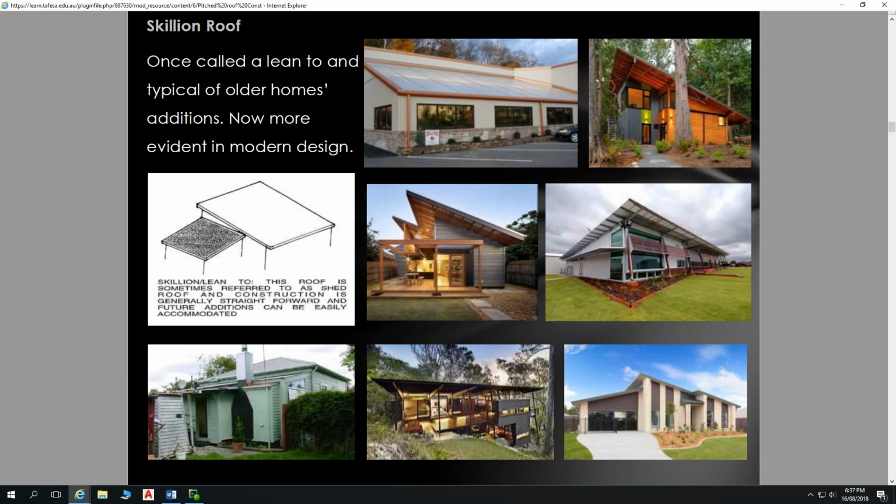So timbers that are durable, because they're still exposed to a lot of weather, and typically our engineered timber, all of our glulam beams and LVLs, don't stand up very well to weathering and can't be used in an external context. So for aesthetics like this, we still have to rely on very large pieces of hardwood timber, which are very expensive to buy. So fantastic aesthetic, but actually fairly expensive to produce.